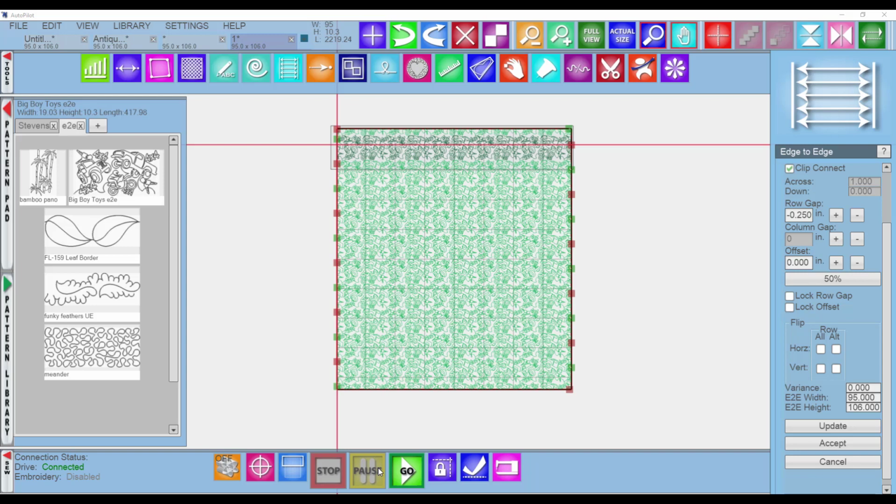This icon is your channel locks, and so it might look a little bit different if you have one of the heads that came before the Mach 3 series, or the M24 series. And so on the M24s, if you click it, it will show you that the head is locked in a vertical path. So now I can only move my head vertically. I cannot move it horizontally.